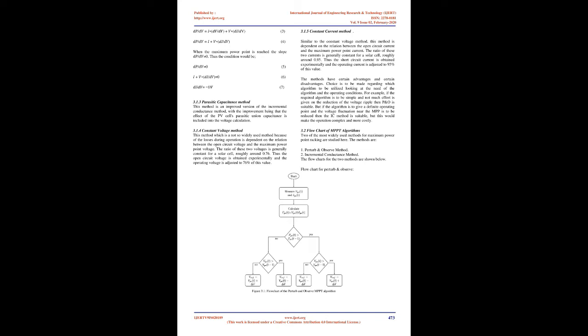Typically, a module is the basic building block of photovoltaic systems. PV modules consist of PV cells connected in series, to increase the voltage, and in parallel, to increase the current, so that the output of a PV system can match the requirements of the load to be powered. The PV cells in a module can be wired to any desired voltage and current. The amount of current produced is directly proportional to the cell's size, conversion efficiency, and the intensity of light.